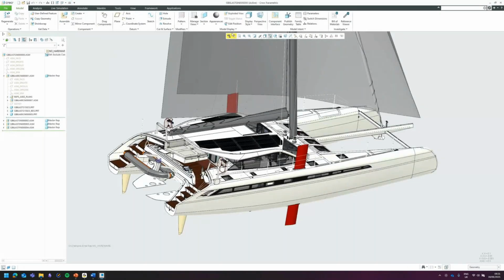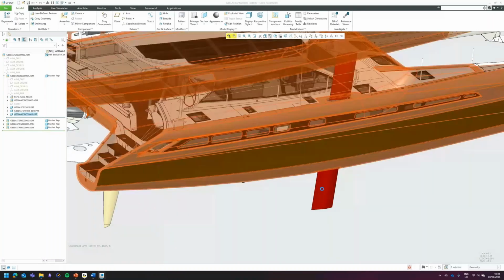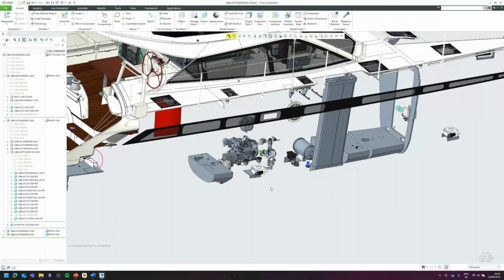Next in here in the graphics toolbar then are visibility states. So as I said, if we were working on a model and we're doing some more design work here, let's hide off a few components in this assembly. Maybe that's it. I'm good. I'm working on this little motor assembly here, but I need some information from the stuff that I've just hidden. What I can do is capture the current visibility. Okay, and if I hover over this, it's going to give you a little graphic to show you what the current state is.